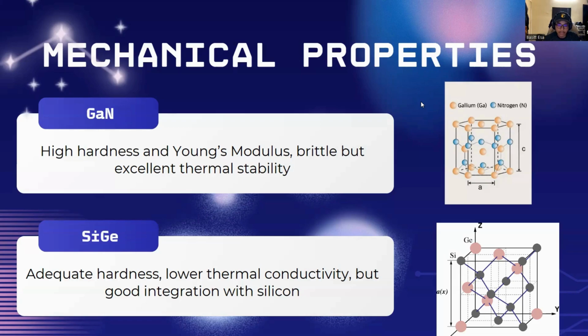In its microstructure, GaN presents a hexagonal wurtzite crystal structure, granting more robustness and dense atomic packing. The nanoporous form of GaN has emerged as a promising material for optical and optoelectronic devices. Although the electronic and mechanical properties of GaN can be adversely affected by common structural defects, such as threading dislocations and point defects, these have been significantly reduced through advancement in material processing techniques, which enhance overall performance.